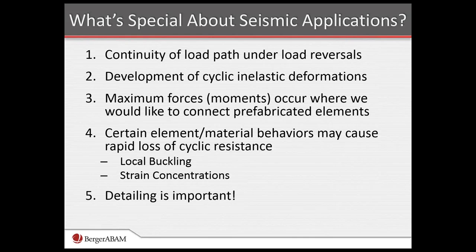As I said earlier, we try to stay just shy of that point with a bit of factor of safety in terms of deformation. Now, additionally, strain concentrations can reduce the inelastic or deformation capacity, and that is what I was alluding to where I said we want to keep the hardware out of the energy dissipation zone if we can. That reinforces point 5 here, which is that detailing is certainly important.